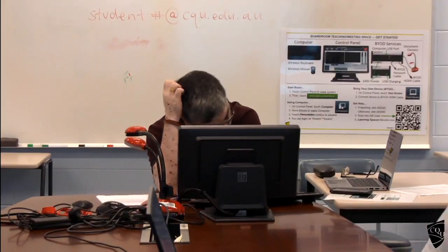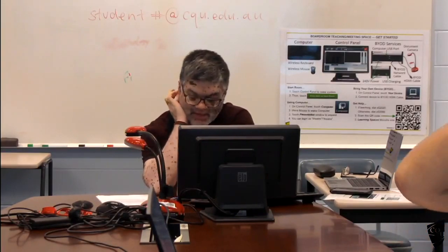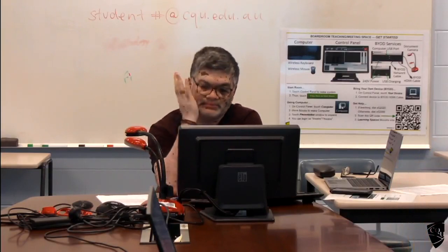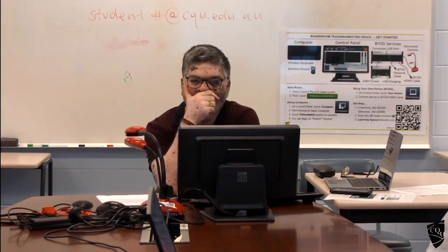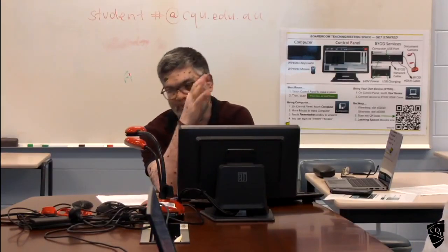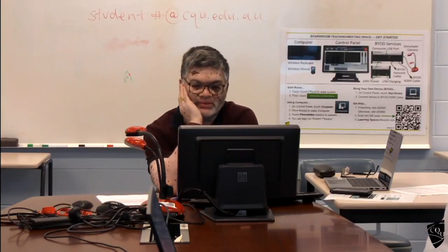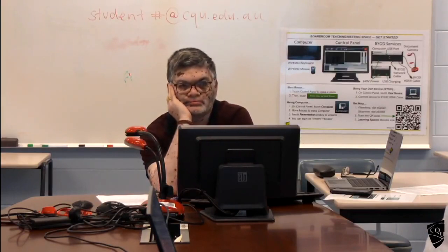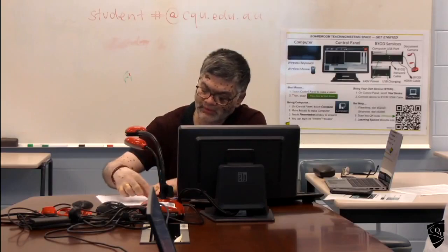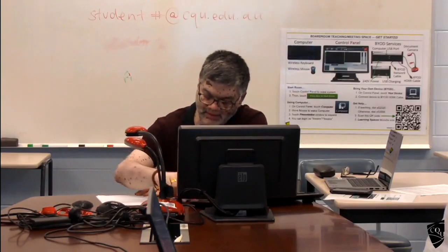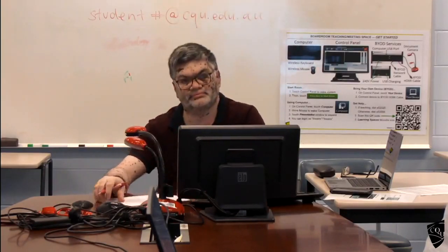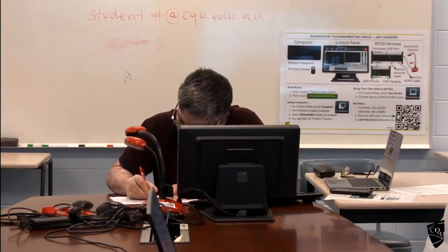Okay, so center to center distance of the columns will be divided into 4 equal parts roughly. It can go a little bit up and down, but if you divide by 1/4, it is good, easier. Okay, so this is for one direction. We need to do the same thing in the other direction.